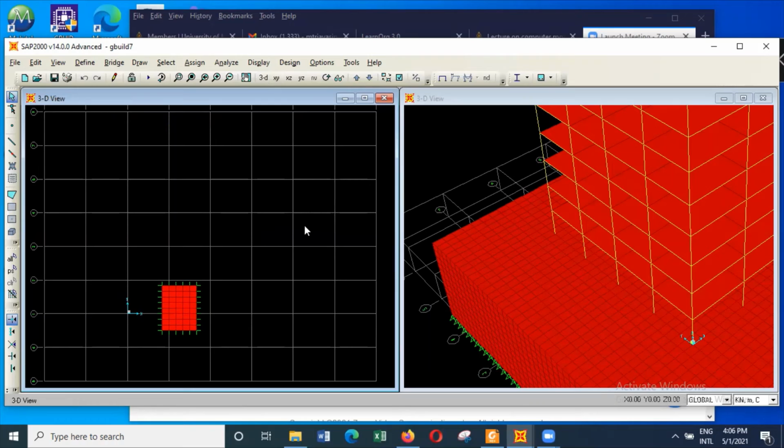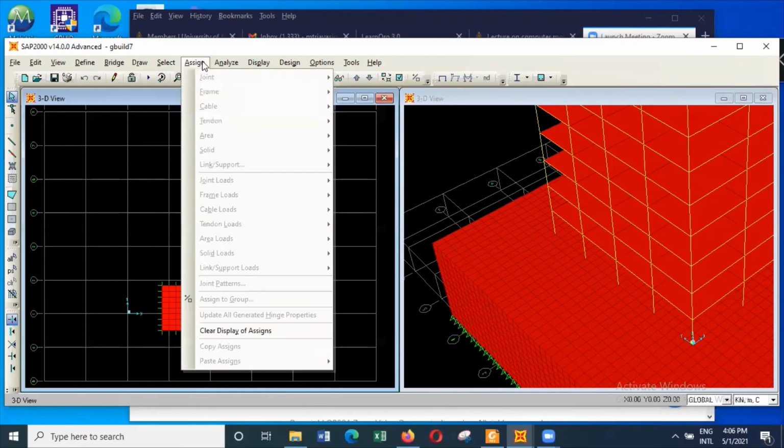Selection only. So that's the only area that we have selected. The column is there, and that's the weak area that we have found, where there's a weak pocket that we cannot remove. So we have to live with it because it's too large to remove and compact. So we have decided to go with a raft foundation where we are going to deal with this weak area with the foundation.